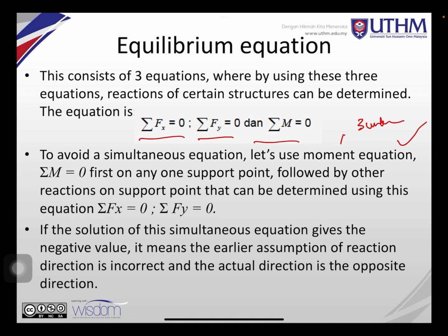Okay, so with this concept of raising these equations, the reaction of a certain structure can be determined. To avoid simultaneous equations, let's use the moment equation, the moment at O, first. It is recommended to use this one first, followed by the other reaction forces. Total moment equal to 0, total Fx equal to 0, total Fy equal to 0.